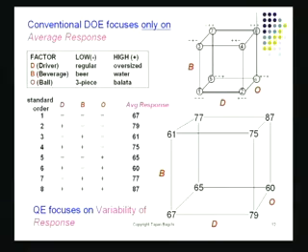So he gave us targets, he gave us loss functions, he gave us the method of system design, parameter design, and tolerance design. Then he highlighted the use of orthogonal arrays, which is something like the factorial experiment, but it is a lot simpler. Then, of course, Taguchi also highlighted the utility of the signal-to-noise ratio.